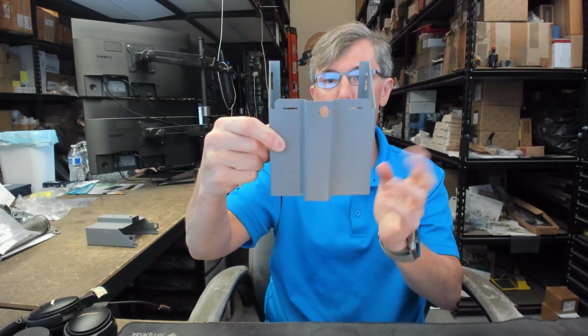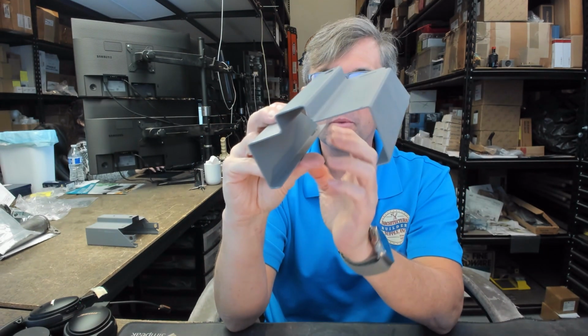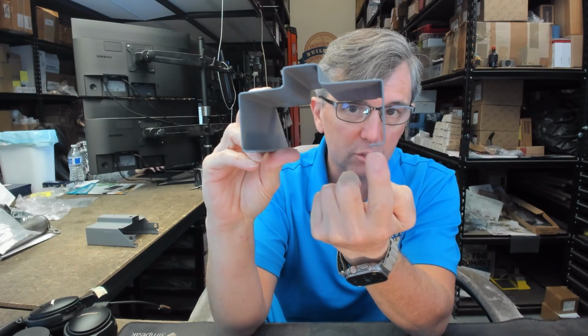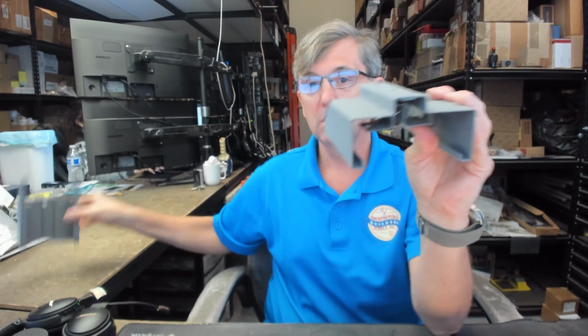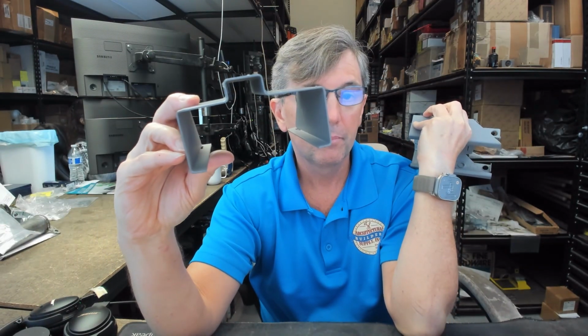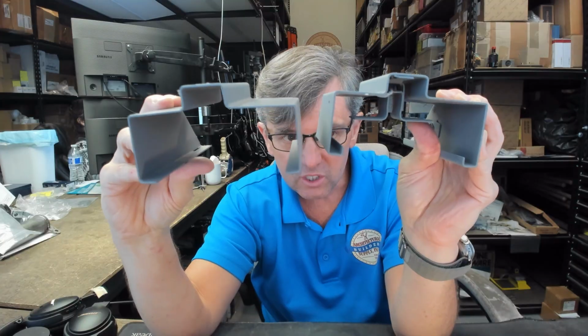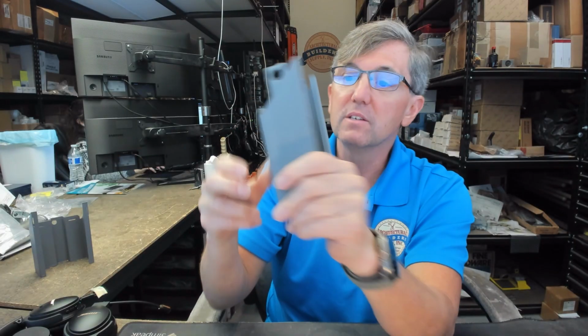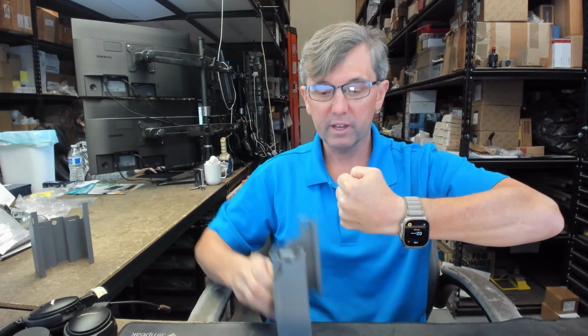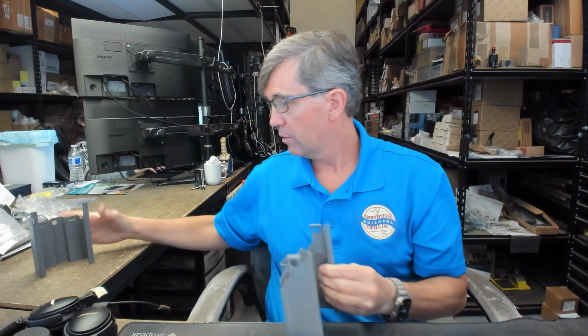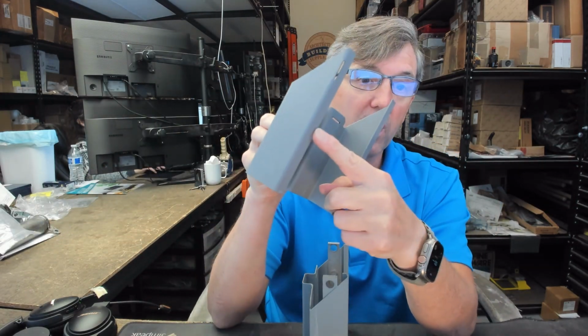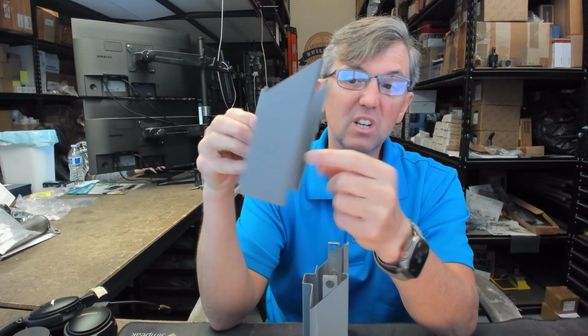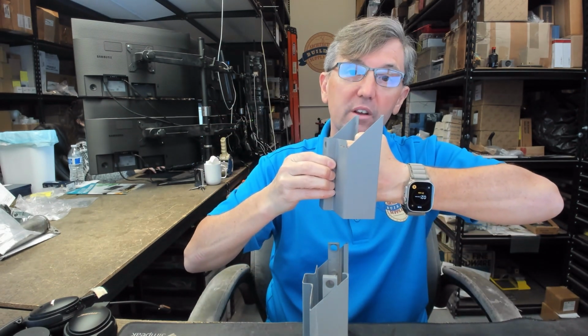So here is a masonry frame. Typical is probably a 4 3/4 jamb depth masonry frame, and what I'm calling your attention to is this right here. That's called a return. Inherent in a drywall frame, which I have one right here, masonry frame, drywall frame. When I put them together, you can see the difference. The drywall frame has this back bend return. That is such that when you have the opening, here's our wall again, and you slide that over, the return of a masonry frame has a tendency to tear the face of the wall covering back.